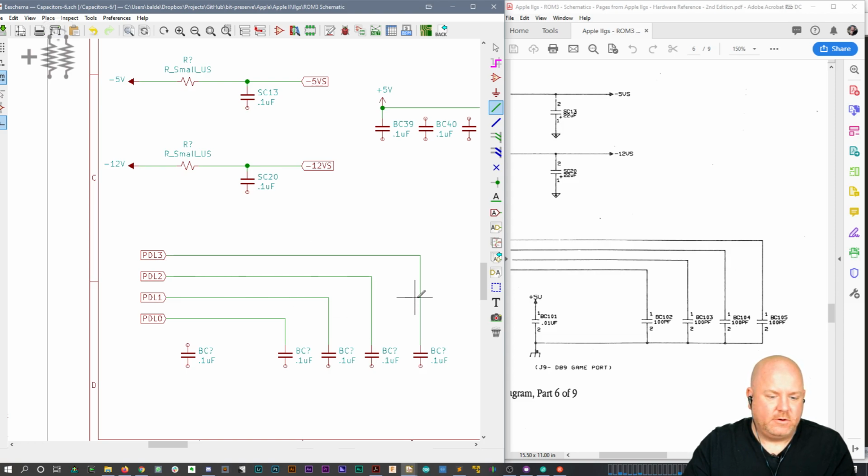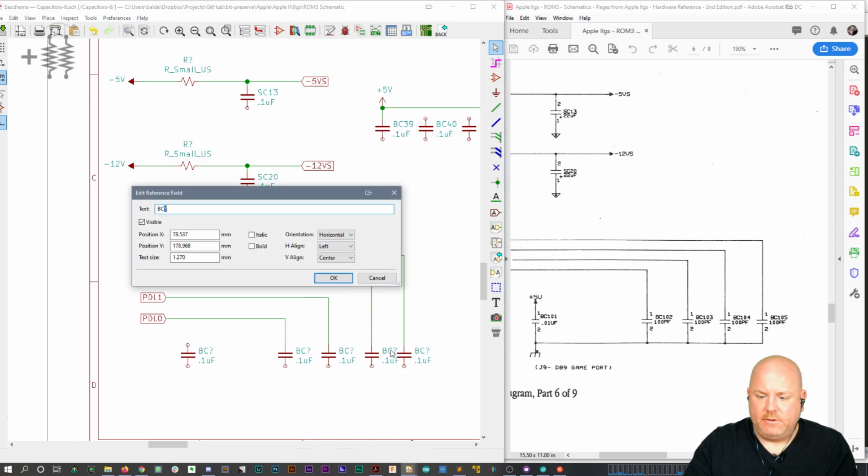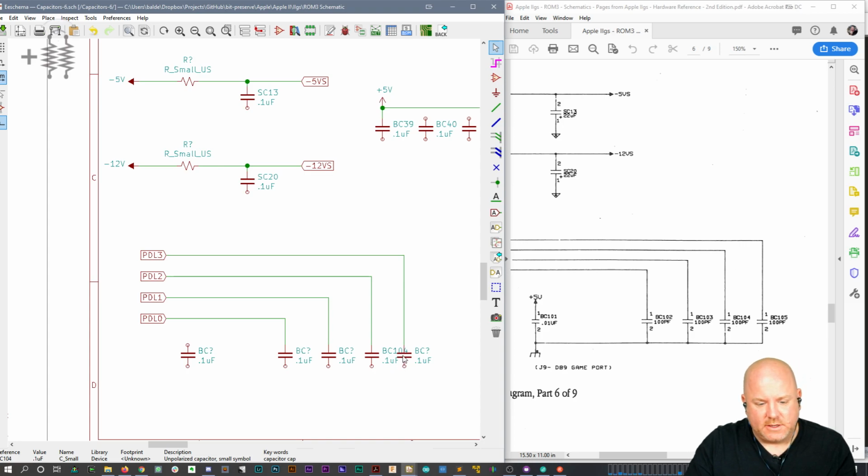Yeah, so if you hover over a wire and hit G, it allows you to move the whole thing around without having to do what I just did. So like if I had left this too close, and then we made this one 104. And it was like, oh no, it overwrites that. So we hit G, maybe G on this one. G. Yeah, that's a lot cleaner. Look at that. That's what we're talking about.